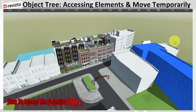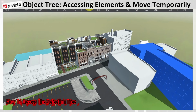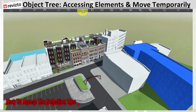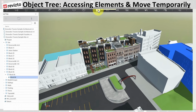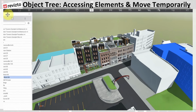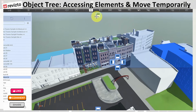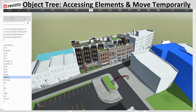In today's episode, Learning Revizto, we're going to take a look at a very important element in Revizto, and that's the selection tree. Under the 3D mode, we have the first one right here by default, which is the selection tree. If you click on it, it's going to open up a panel for you, and the shortcut for the object tree is Control B. If you hover over the top of the object tree, it's going to change from arrows to a move tool, which means you can move the panel, dock it anywhere you want, and fix it where you want to put it.